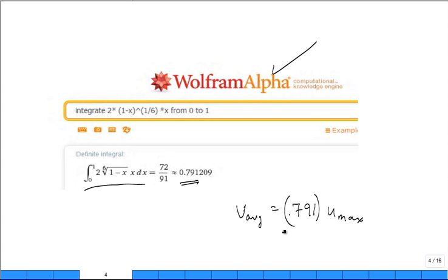Okay, so this velocity profile, if I plot it, it's more like a turbulent profile. It'll be flatter, and the average will be 80% of the maximum, which is not that different from the middle, in the core. It's pretty flat in the core, that velocity profile. Okay.